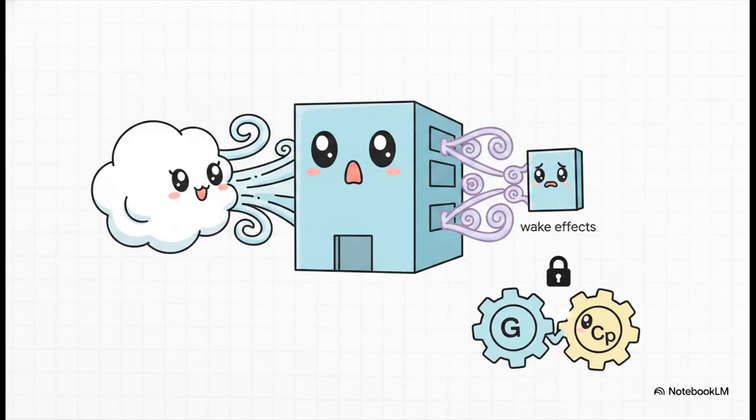And why are they locked together? Because, and this is absolutely crucial, you simply cannot separate the gust from the suction. Complex wake effects and separated flows around a building just don't correlate directly to a gust in the approaching wind. When wind hits a building, it separates at the corners, creating massive turbulence and shear layers. The suction ripping a panel off a wall isn't happening just because the wind blew a little harder for 3 seconds. It's happening because of the specific aerodynamic disturbance caused by the building itself. The standard demands you use that combined GCp value to accurately capture that localized peak negative pressure.